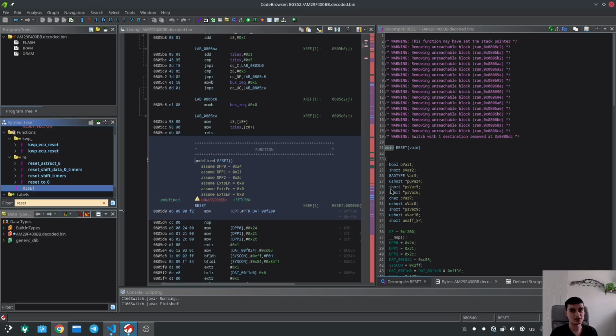Now you may notice, what is this big purple section down here? This down here is actually the Mercedes application layer. Siemens have exposed 2 or 3 functions which Mercedes had to implement, which is for their entire gearbox code. So essentially the entire application of stepping through the logic of reading everything on CAN, then processing it, then processing all the solenoids as to pressures and stuff like this, and then doing anything else that Mercedes sees fit, is all done on one thread. So I can show that here.